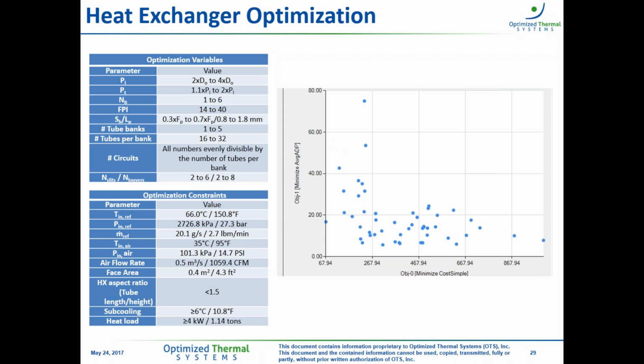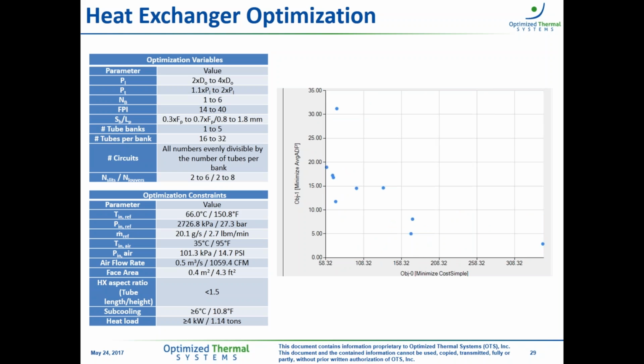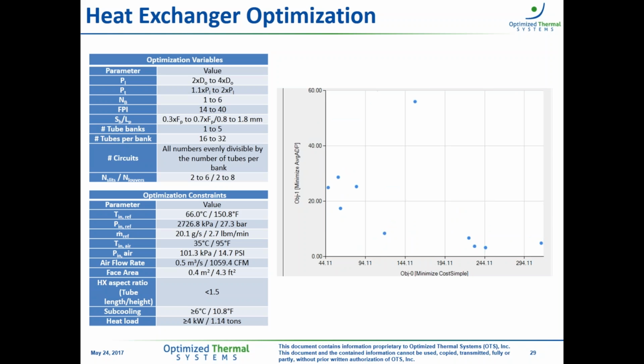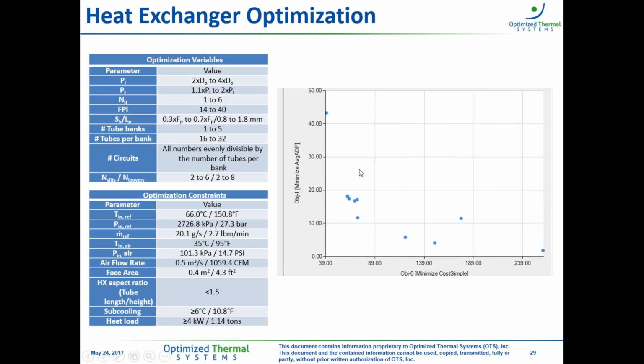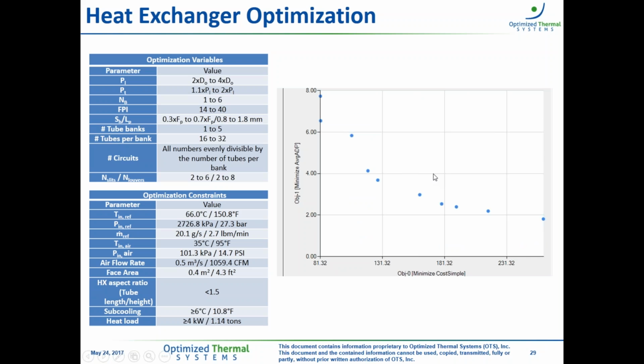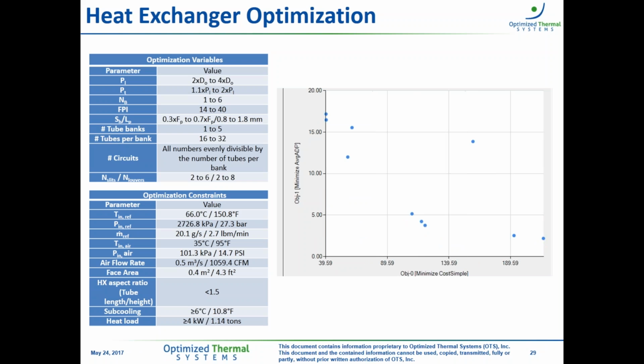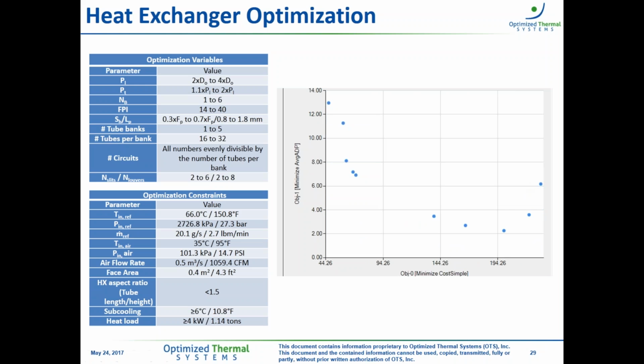And what we did with this problem definition is apply a multi-objective genetic algorithm solver to solve this problem for us, using heat exchanger modeling software to predict the performance of each candidate design. Just as a graphic here, I'm showing on the right-hand side a visualization of what that process might look like if we look at a genetic algorithm solve a problem through each iteration as it learns from one to the other how different design parameters affect the performance of a heat exchanger.